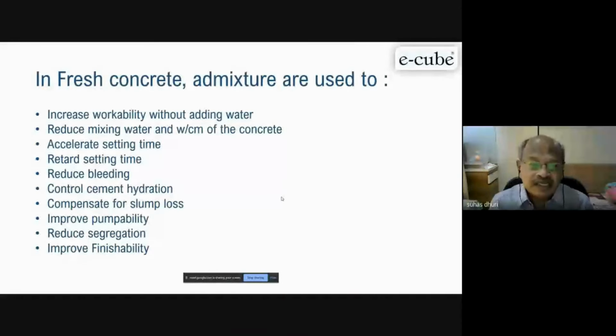But it's possible. Today we are working like this. Concrete can be delayed for 8 to 10 hours without having any cold joint. We can proceed for the entire pour, maybe for 3 to 4 days or 5 days of concrete. So that is possible. Reduce the bleeding.